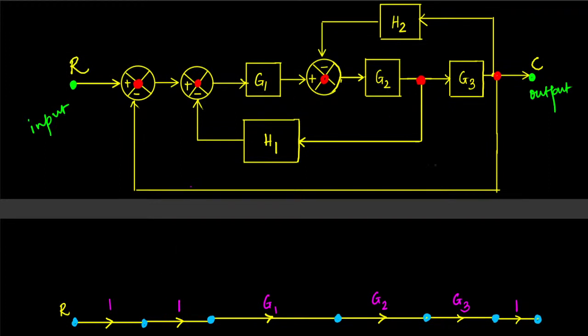All right. So now look at this node which is depicting this one here, and from that we also tap a certain connection. So this is a branch point, right? From this we have another transfer function through which we have a feedback. So this signal starting from here, let's say this is C, becomes H2C, and that is entering this node, but with a minus sign.